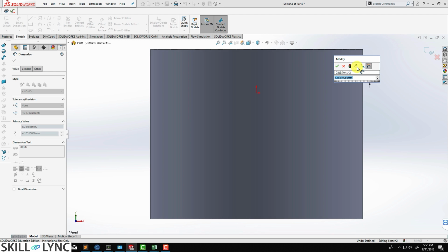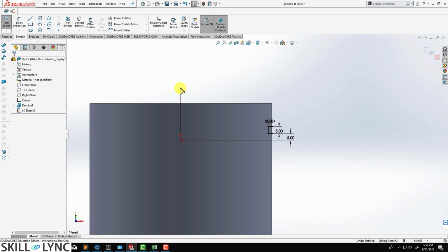Now we're going to select the end line of the piston and our slot, and we're going to use make collinear so that we align the slot correctly. So now you can see that the groove has been fully defined. Now what we can do is we can use the revolve cut option to basically create the slots. We need an axis for doing this, so let's create a vertical line which will be used as an axis of rotation for the cut operation.